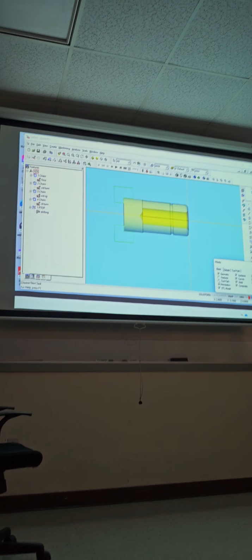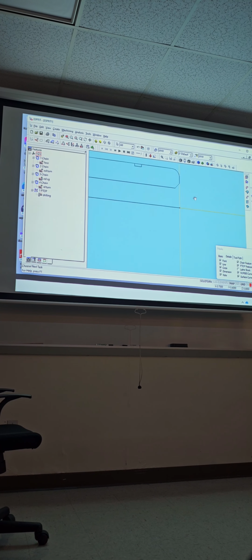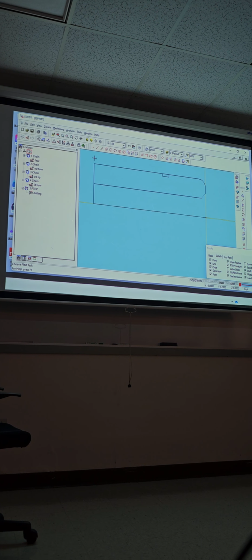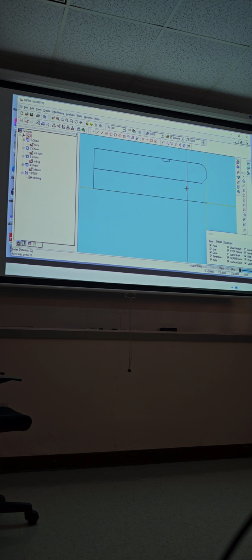So stop simulation. We're gonna go features off, tool path off, lay stock off, and let's do some geometry. On the geometry, line 1, from the face, back, 2.0, enter. And now I'm gonna find that point, intersection over here. So I'm gonna go point, intersect, this one and that one. I'm gonna go ahead and delete that vertical line so it doesn't get in the way.